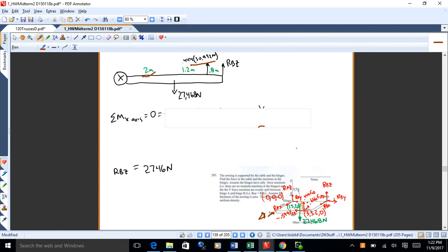So what we're doing here, we're looking at it down the y-axis first. Basically what you get is a beam extending to the left. Then I come on over and I look down the x-axis, I get a beam extending out to the right. And I can successively then solve for the cable force with the y-axis and RBZ with the x. Now I want to get one more.